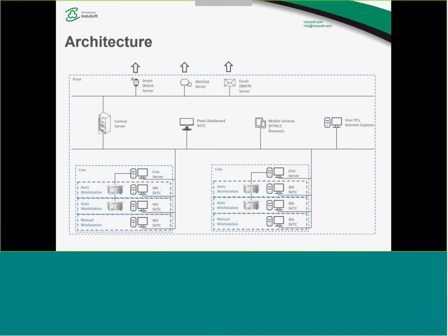This is the architecture of the system in a different view. So you have a central server here running InduSoft Web Studio, which pretty much consolidates information from the whole plant in a single central server. It's also the server to plant dashboards, so large LCD displays that you can strategically install throughout the plant. And you do not have to install InduSoft in those computers. You can use the thin client solution from InduSoft, so it does not require you to install InduSoft, the application, or the license on the plant dashboard stations, and you can have one or multiple.